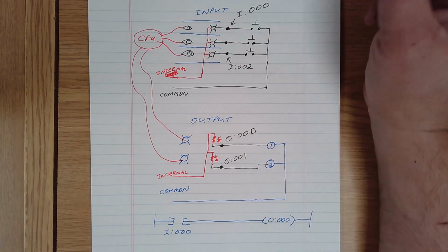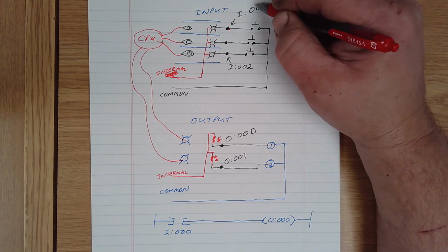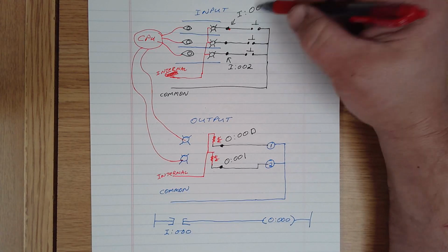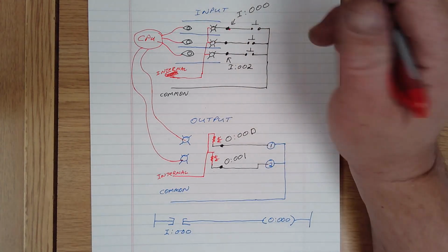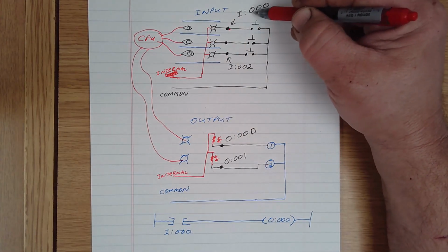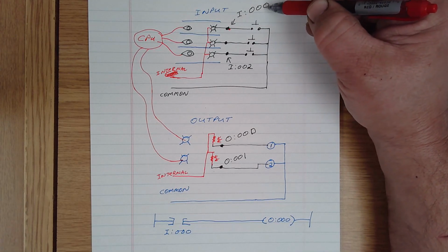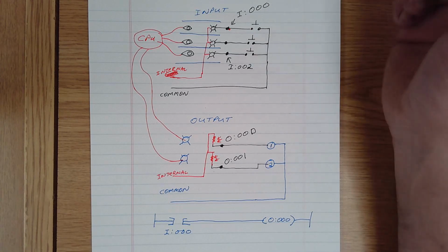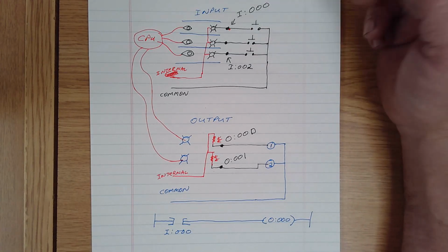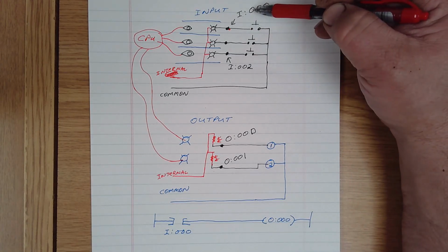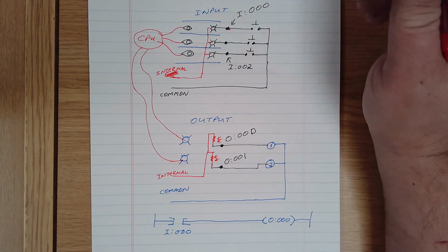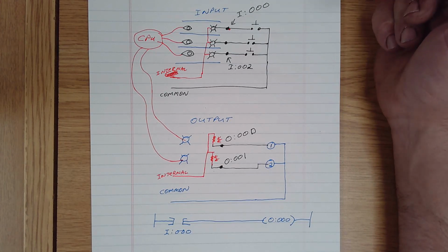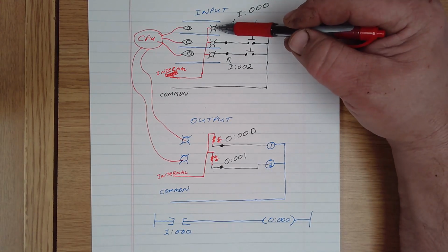If you've got a larger PLC, sometimes the first digit will be which card it is on, and then the next two are which address within the card. There's a variety of different addresses that get used, and it's PLC specific, but the generalization is you're going to have an input, and then you're going to have an address or a physical location, if you will, that the PLC is looking for.